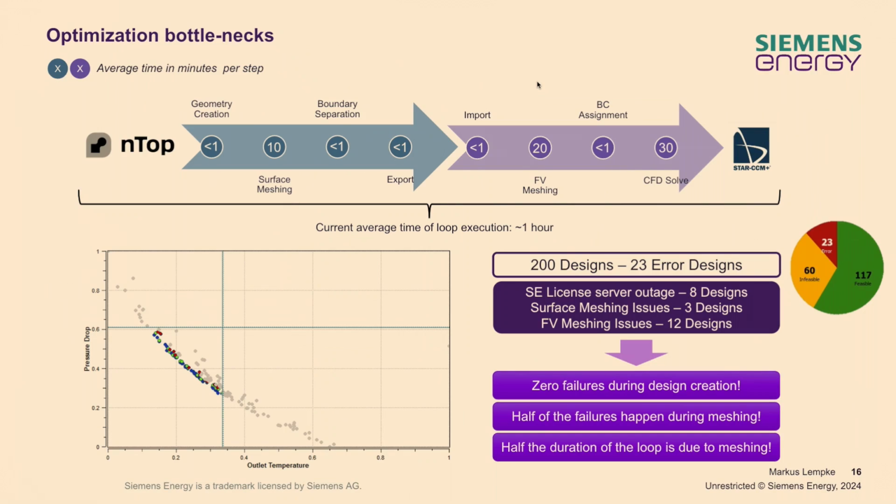In this case, I went for a Pareto study to figure out where I really want to go. I have 2 conflicting targets, pressure loss and heat transfer. As you can see on the bottom left, the horizontal and vertical lines denote my limits that I have to stay under, and only a very small portion of the Pareto front is in the area where I need to go.